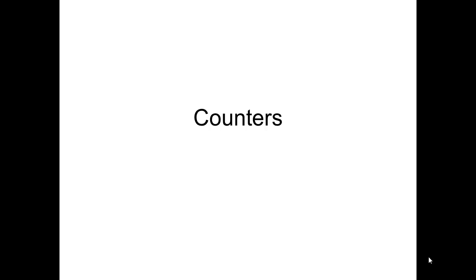We can also use counters to set up output frequencies based on what the input frequency is. So we can split frequencies in half. We can split them into sixth. We can do divide by 10. Do all kinds of different stuff with counters. So let's take a look at how counters are set up and what they look like, and we'll do some